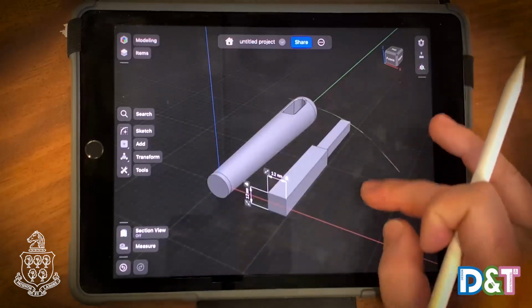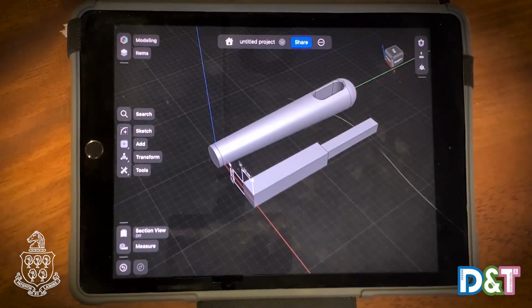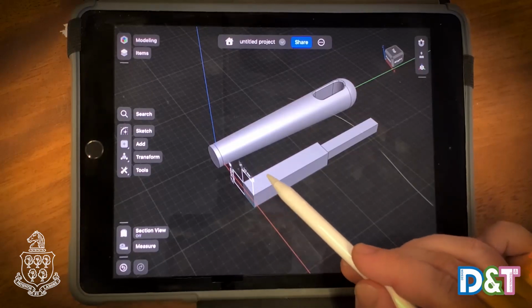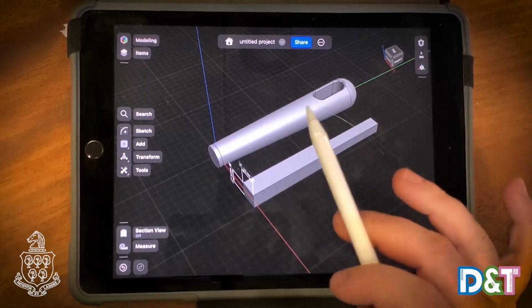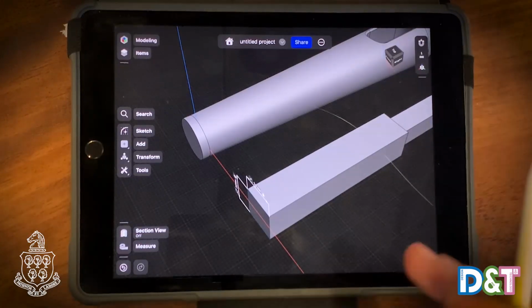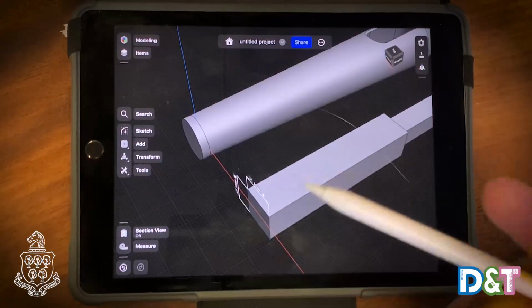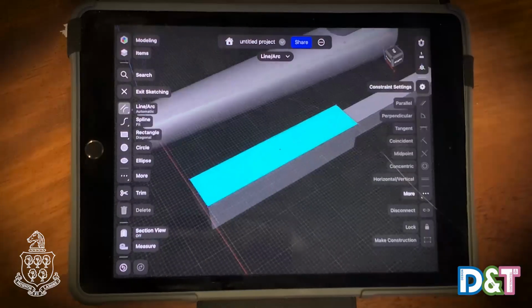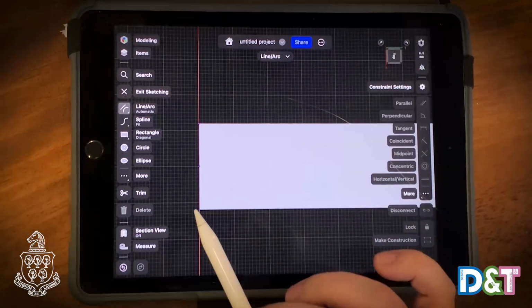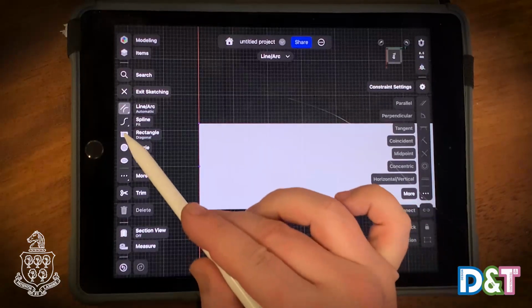So we've got a nice starting shape for the blade holder. There's actually a small thin cutout for where the blade actually goes, which is in this thicker end. So I'm going to show you how to draw that one. With the finger again, we're going to double click on this surface. And then we're going to need to draw a 44 by 2mm rectangle.